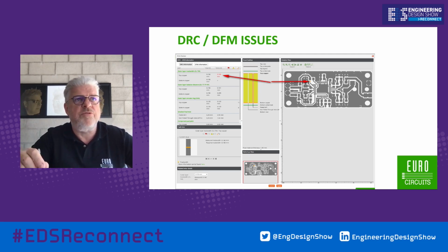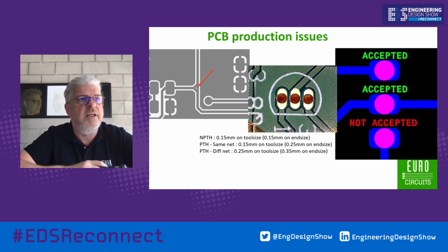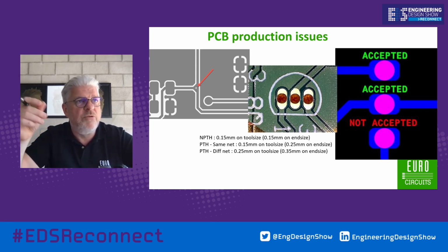And what can be issues? PCB production issues can be like this. The small spot where the red arrow is pointing is these little openings in the copper. They are not so annoying for you, but they are very annoying for us, and they scramble up our production process, because in the developer, these parts of the dry film get loose, and they may land somewhere else where they create problems.